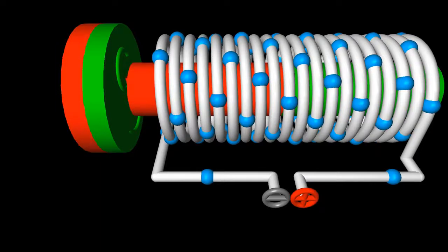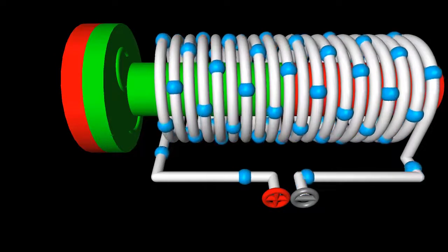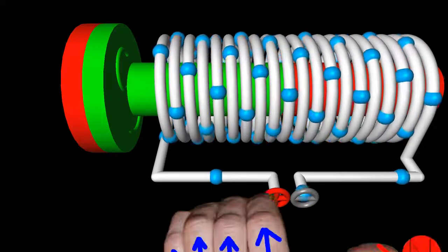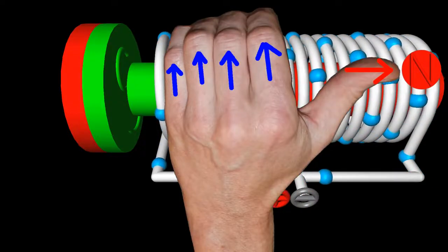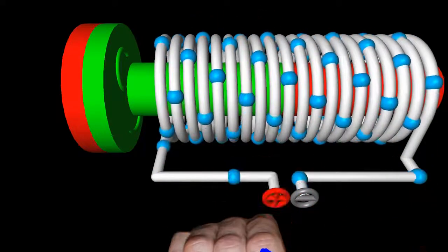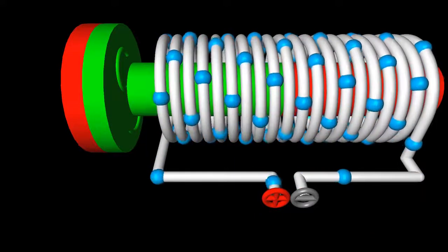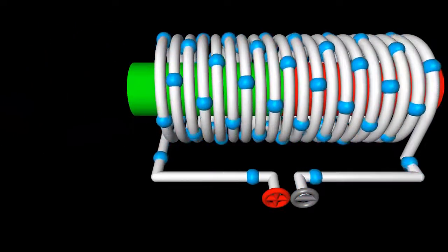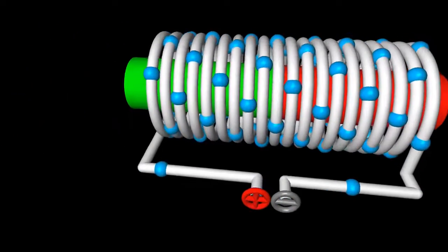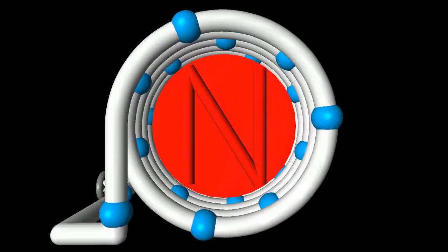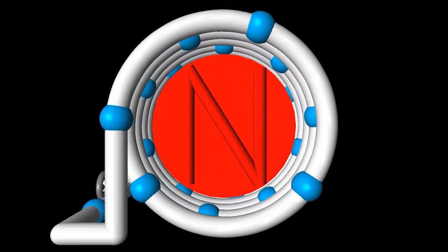Now it is indeed swapped. The positive terminal is on the left side of the electromagnet, the negative terminal on the right. The electrons are now moving from right to left in the solenoid, and by using your left hand you can determine that the place of the magnetic north pole has changed with changing polarity, it's on the right side now. According to this, the magnetic south pole is on the left end, which is why there is a repelling force between both objects. The flow of negatively charged electrons rotates clockwise when looking on the end where the north pole is located.